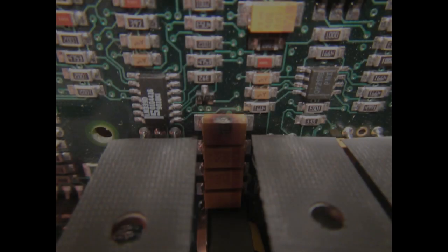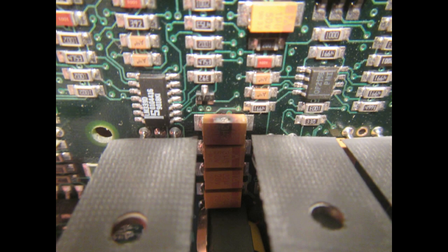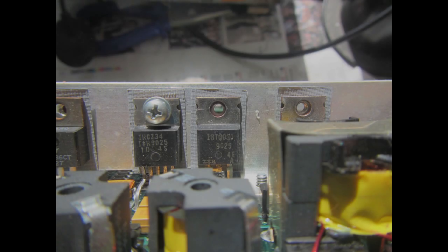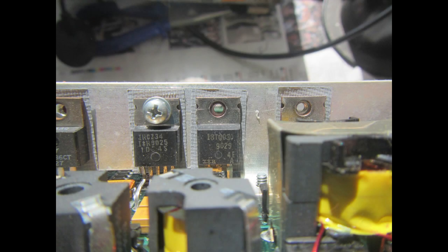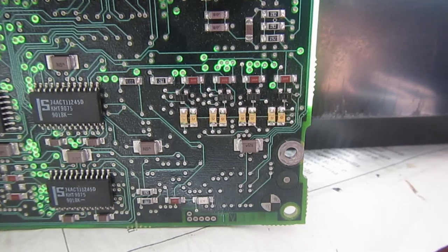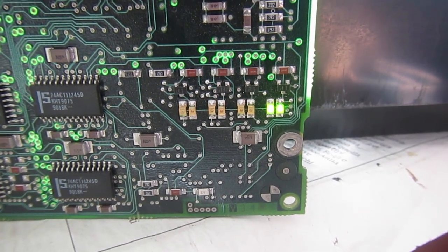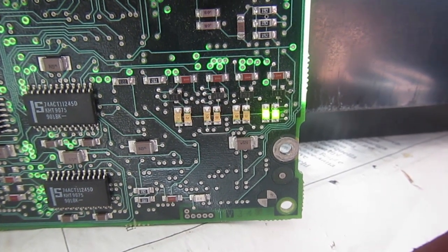After removing the heatsink, we can remove the back capacitor and replace it. Then put back the heatsink. After tightening each of the component screws, we check with the multimeter that none of the tabs shows any continuity with the heatsink. Okay, then I have just connected the main power input and tried to power up again.